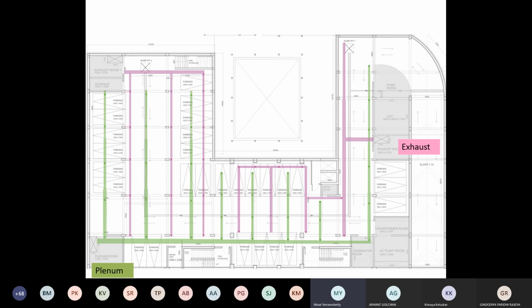Now, first of all, understand why I reduce my duct. As I said, to give me more head space. Because if it is more depth, why would I want to spend more money on larger ducts? That is one reason. The second reason is, if I have larger ducts but lower volumes of air, my pressure is lost. You're getting my point, guys?